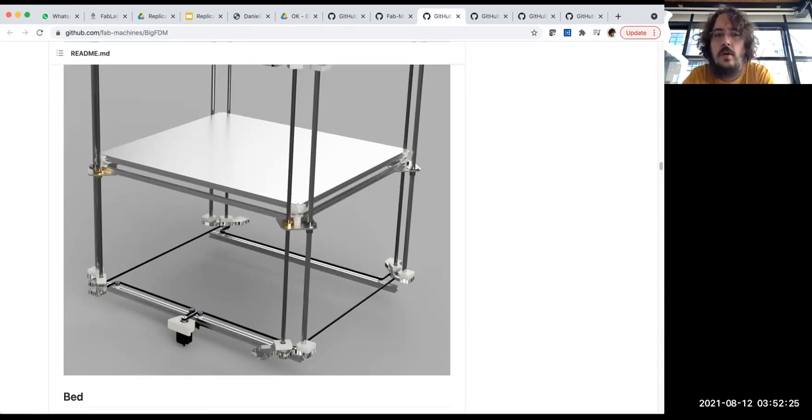This one was already quite complex because I needed to make sure that all 4 points were almost the same height, so the motion would not be blocked by things not being flat. The trapezoidal brass nuts here will create lots of friction if things are not flat, and then it will simply stop.